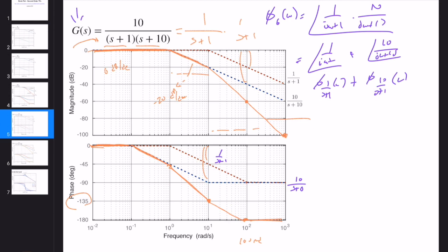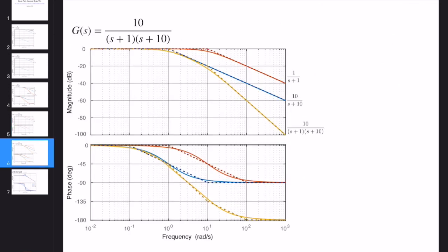For all second order systems, phase starts from 0 and goes to minus 180 degrees. But of course, if the system is stable, minimum phase system. Okay, yeah. So now we are done with the overdamped case, and as you can see, it's not that hard. We simply decompose into subparts which are first order, and we already covered the details and features of first order systems. Okay, so let's look at the results.